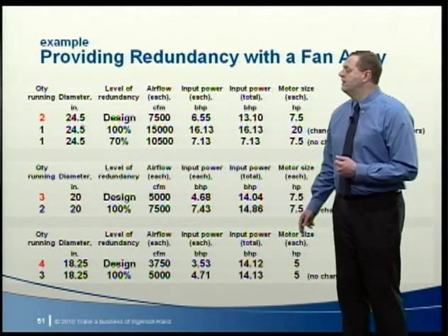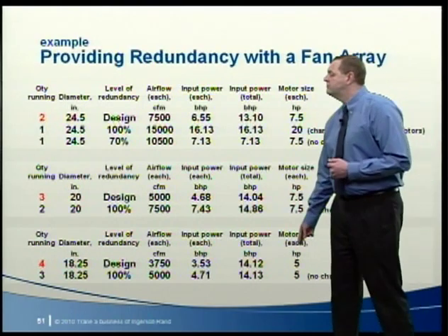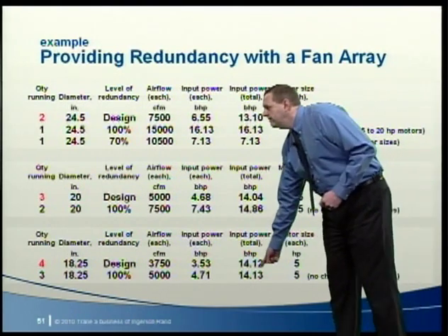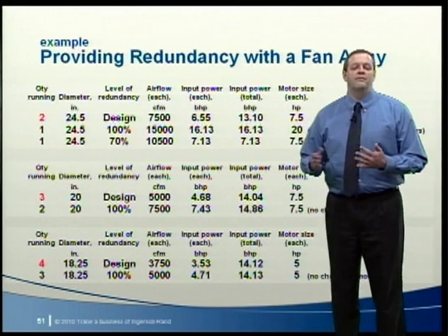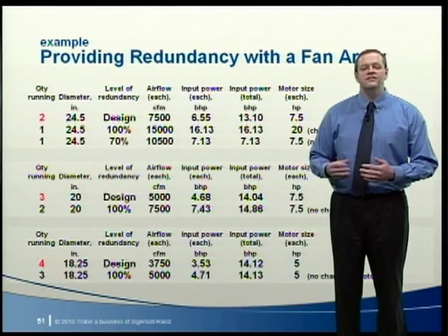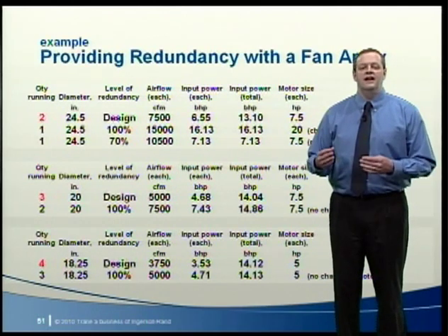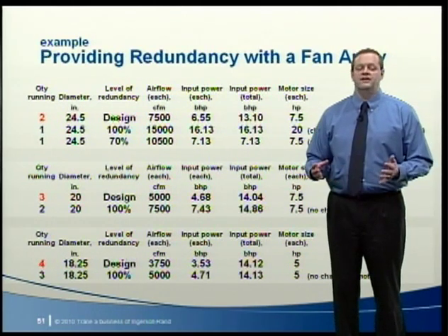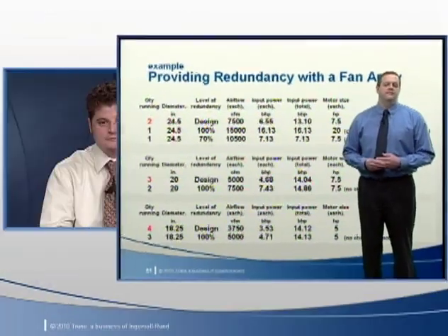The 4-fan array requires the lowest total input power when one fan is failed, but it requires the most power when all fans are operating. So assuming that a fan will be fixed or replaced when it fails, it seems like you would put more emphasis on how the array performs when all fans are operating, rather than when one fan has failed.